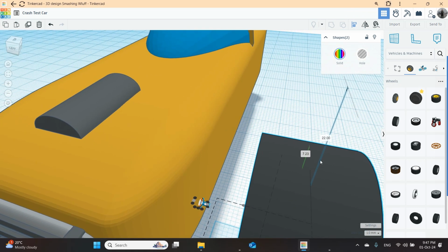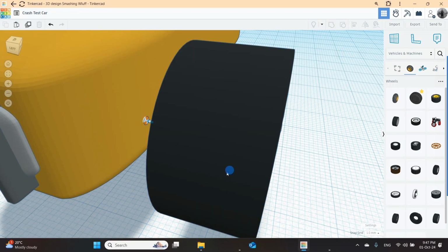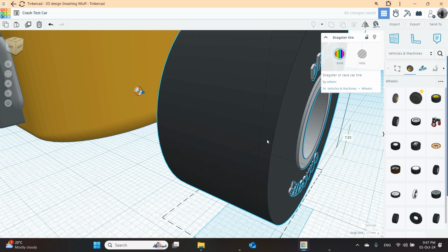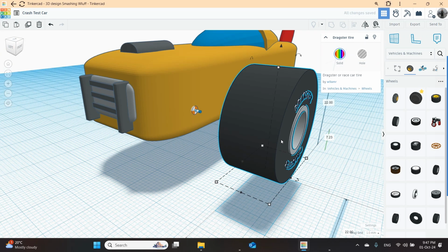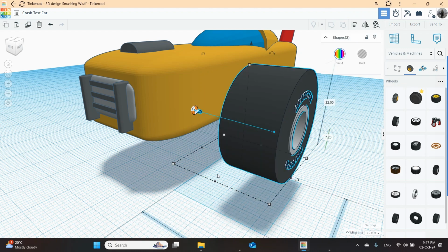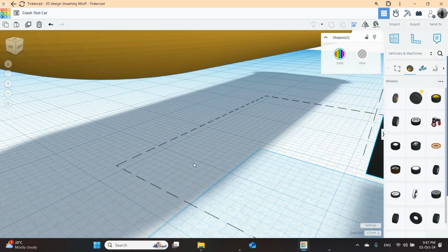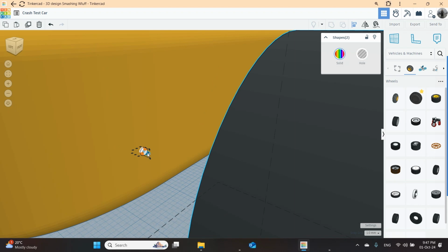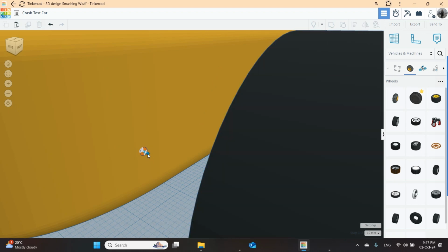So one more time, in case you didn't catch. I have here the wheel. I need it to be aligned. So Shift, I choose the connector, I choose the wheel. Align. I click the connector and I choose it to be aligned to this center.